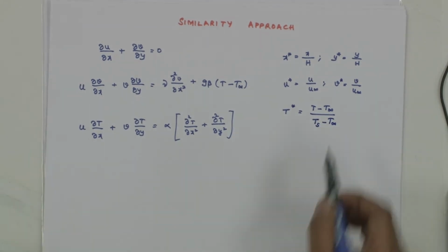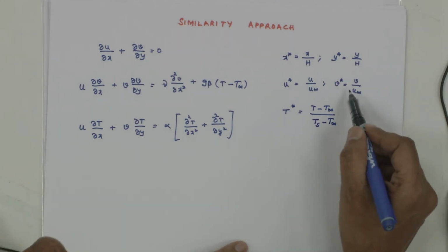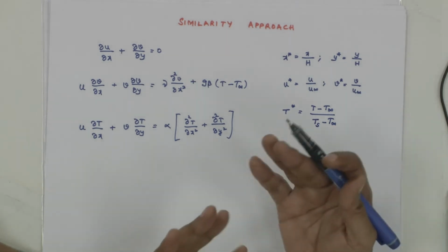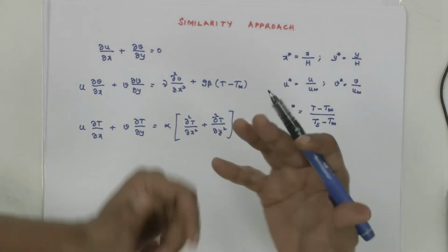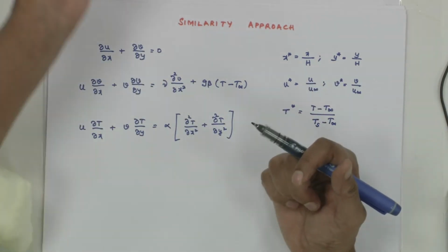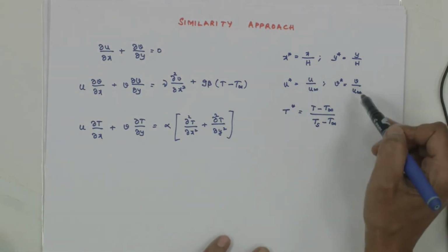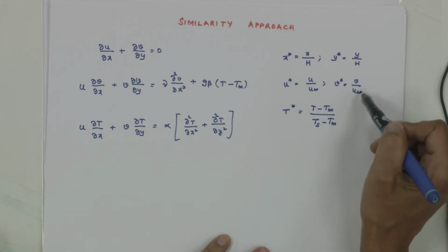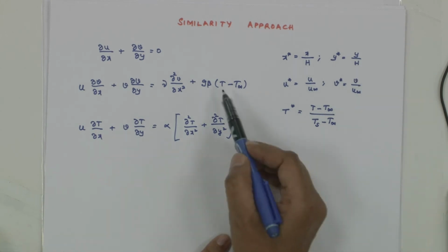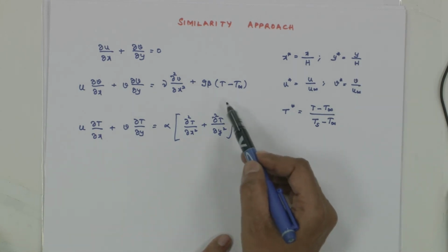See, unlike forced convection, I will not know the u infinity in natural convection. U infinity can be visualized as a characteristic velocity, maybe the peak velocity in our graphs that we saw earlier. But we will not get it directly, unlike forced convection. What we really know is the delta T, that is Ts minus T infinity.